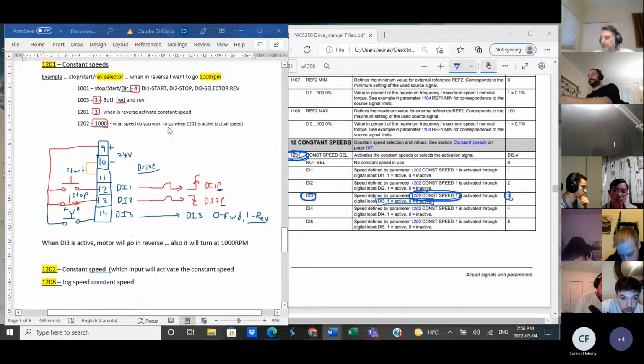We have to input the nominal amps, nominal volts, nominal speed, frequency, all that. That's how it knows. And also, every now and again, it does a self-diagnostics, and it actually magnetizes the motor. You're going to see a number 2025 appear, which is called first start, and it actually does a diagnostics itself. So yeah, it needs to know that. You're absolutely right.